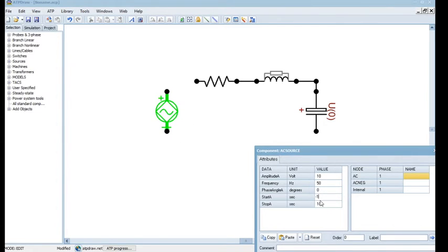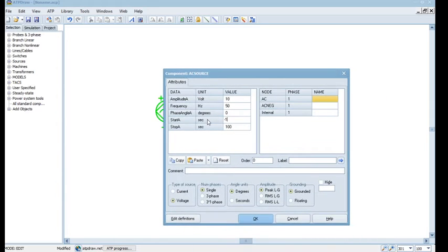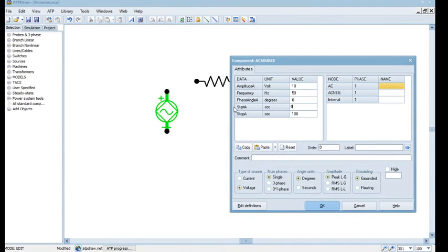When it is -1, it will start with steady state. But if you want to make a transient happen, you can just specify a time, let's say 0.1, then the source will start at 0.1, else it will be always 0. Since here we want to start at 0, we'll specify 0. But just keep in mind, -1 will start with a steady state, but when you say 0, the source will start at t equal to 0, meaning a transient will be observed. So that switching element we are imbibing within this source. Why are we doing this? Because it's very easy to assign. We'll get to that source thing later.